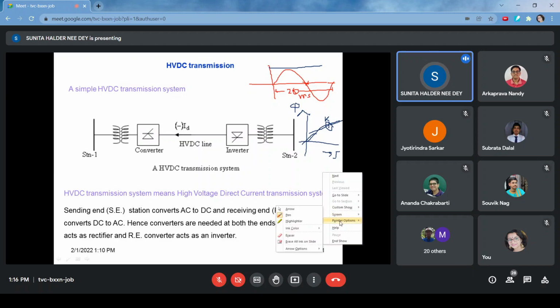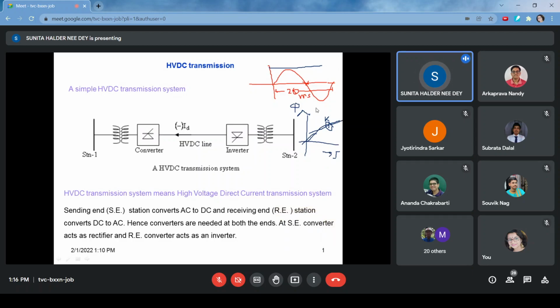Whatever I have explained to you about the transformer core, it is not happening from the harmonic. You always write that in the report, but that is not the thing. It is happening due to the nature of the magnetic material, the nature of the core, because all the magnetic molecules are linearized at the first stage, and near the saturation there are no further magnetic molecules to get linearized. For that reason, that comes.